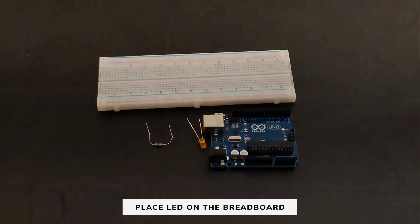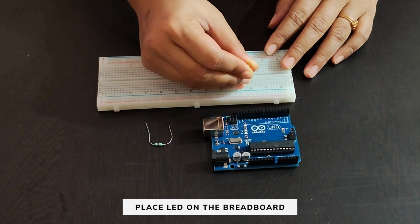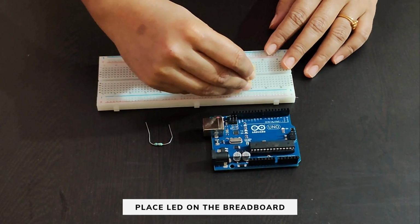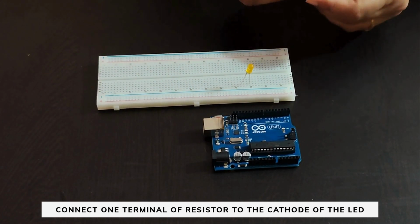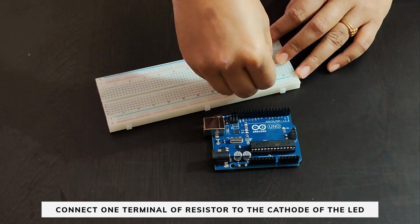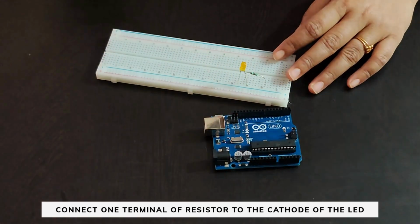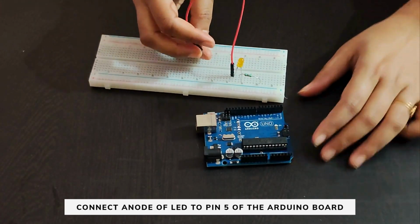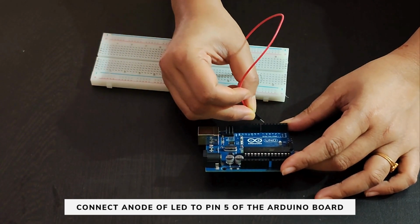So first of all, we will place the LED on the breadboard. Then we will take a 1 kilo ohm resistor and connect it to the anode of the LED, and connect the other terminal of the wire to pin number 5 of the Arduino.